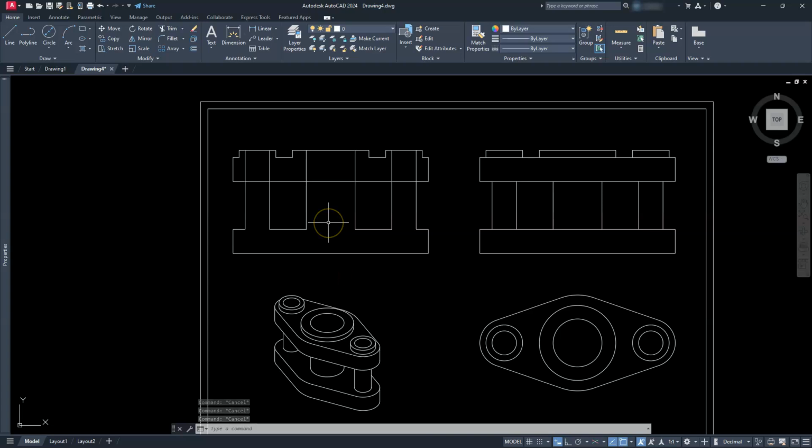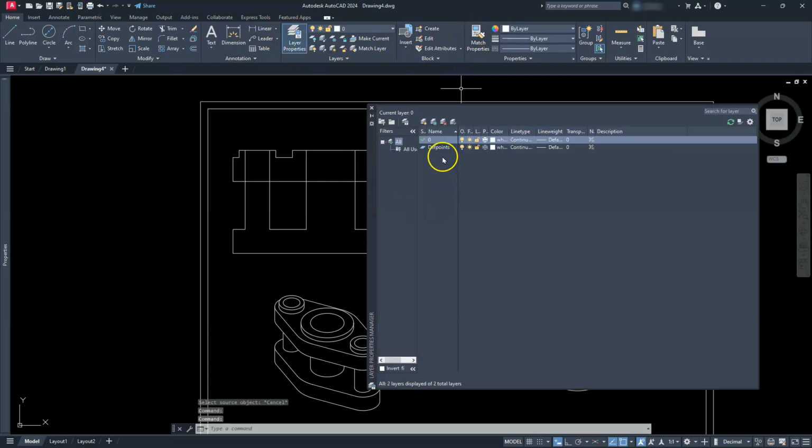Now let's go ahead and put the hatch on here, and we can decide if we want to create our layers or things of that nature. If you want these to be on layers, just go up to the word Hatch, up to Layers, and then we can create a layer for all of this stuff, right? So we can create a hatch layer. We're going to have to create a phantom line layer.